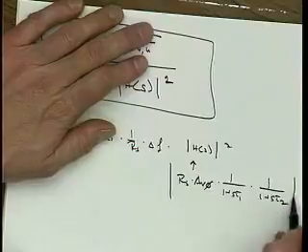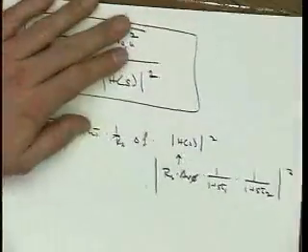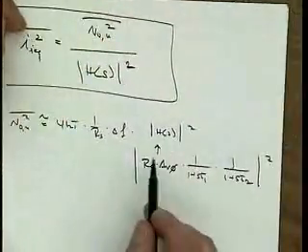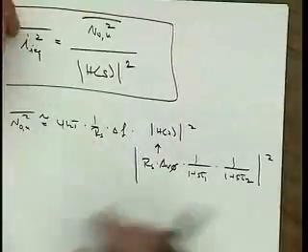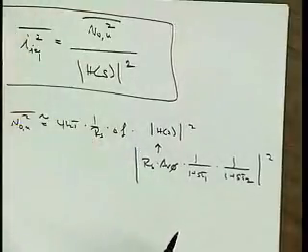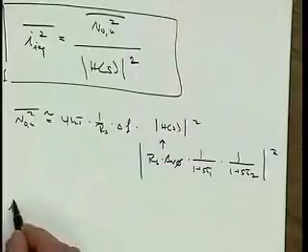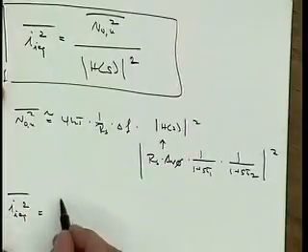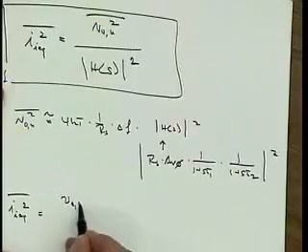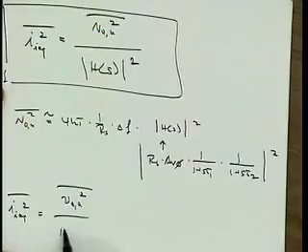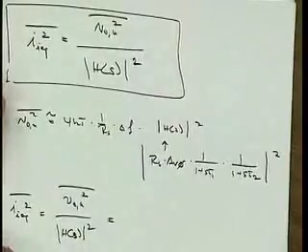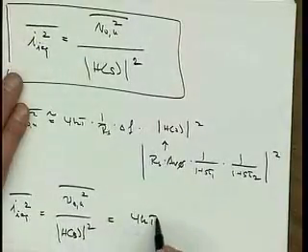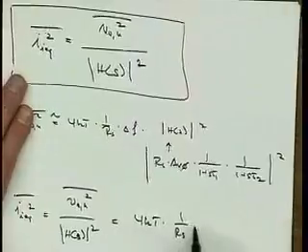Now there were other noise sources, but we recall that the Rs was really the dominant one, so I'm not going to write that. So what is I_EQ? Well, I_EQ squared is simply equal to V_on squared over H of S squared, and that is equal to 4kT times 1 over Rs times delta F.